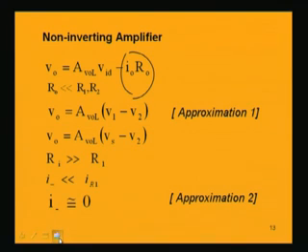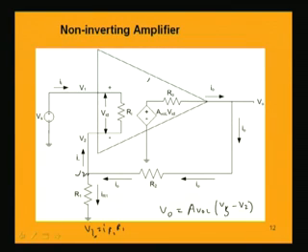That means, if we consider these two resistances Ri and R1, the current has two parts, one through Ri and the other through R1, but this resistance is very high. So, we can practically assume that all the current that is flowing is through R1. That means, the same current I0 is flowing through R1 also. I negative is almost equal to 0.